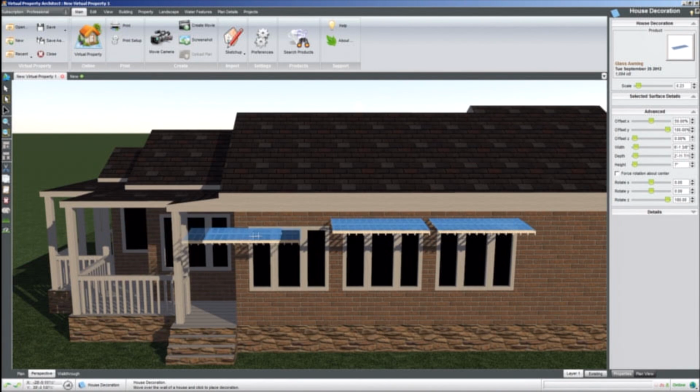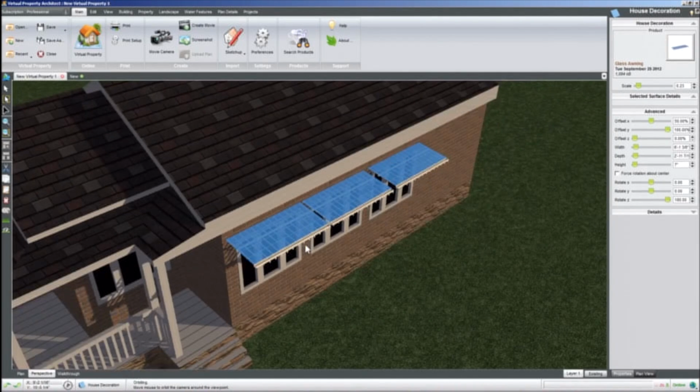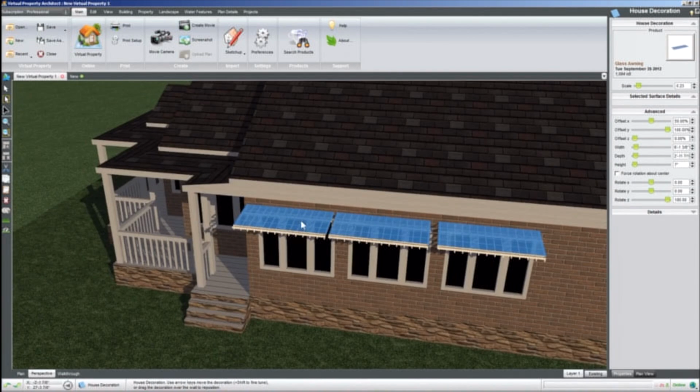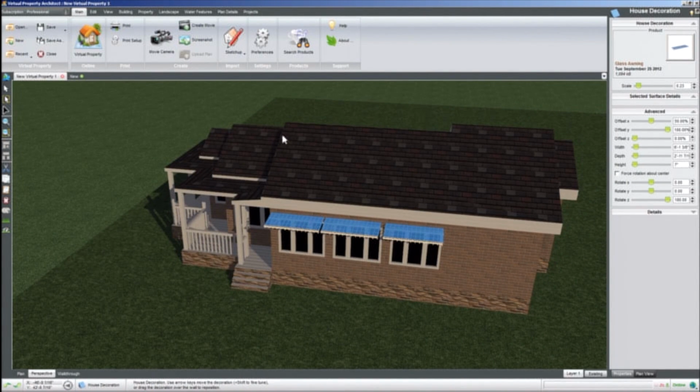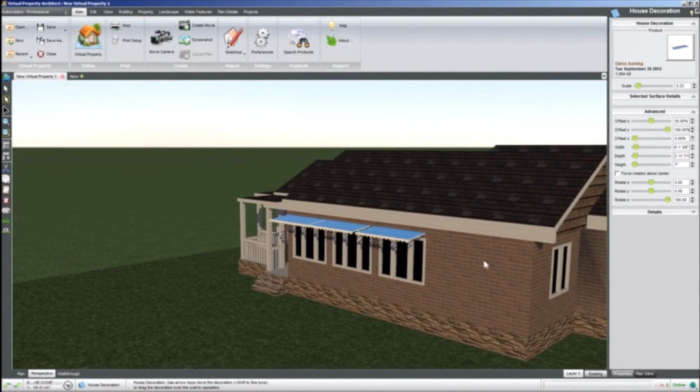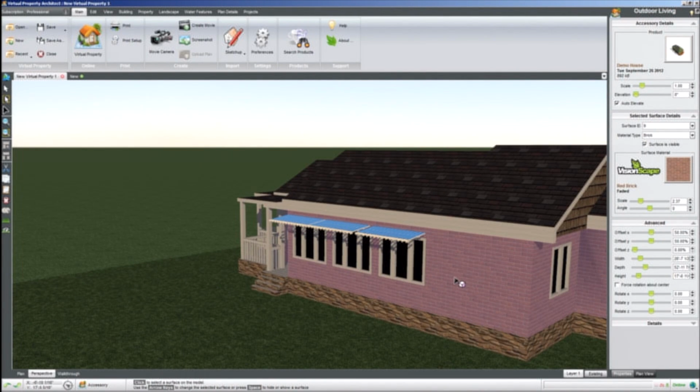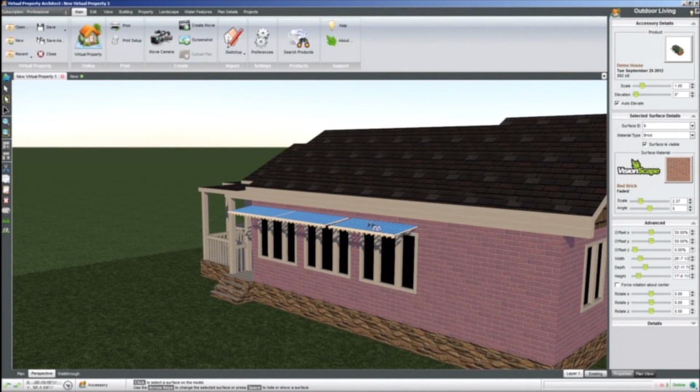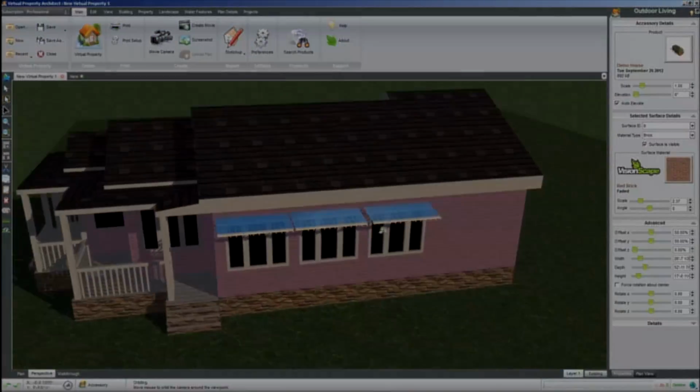But with a SketchUp model there are a few little kinks, so just be aware that Visionscape houses are a little bit easier to work with when mounting objects. If you're going to be mounting objects like this to a SketchUp structure, take that first step where we fixed back-facing polygons dead seriously. If this face were actually the back face and we attached this awning to it, it would be facing into the house, and that's not what you want.